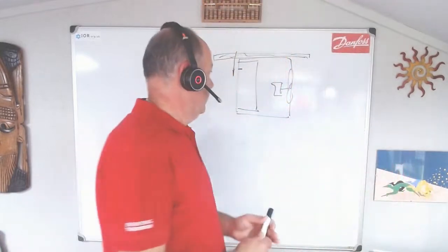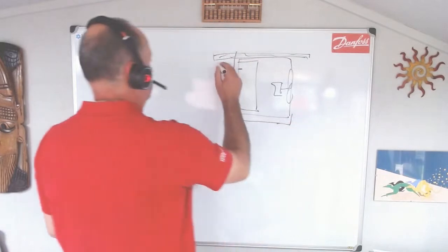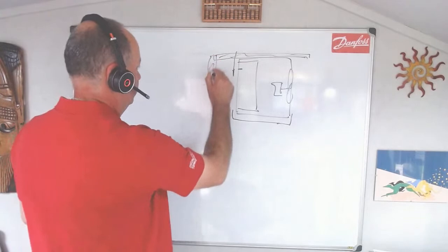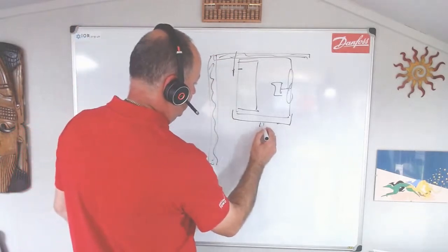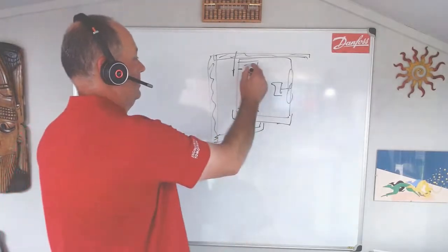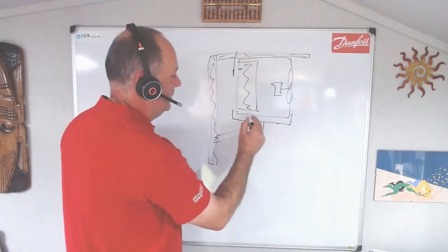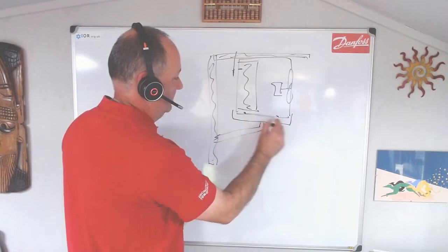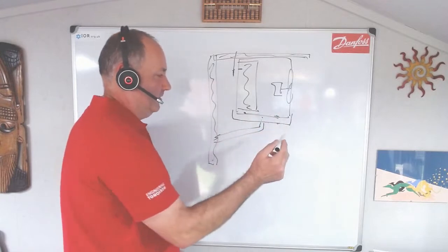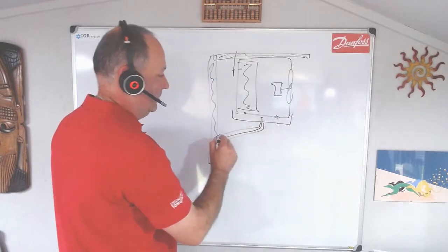Okay, drain line heaters, must they operate all the time? Now, obviously, let's play on the whiteboard a bit more, as we've got the picture of our evaporator up. Let's do the cold room wall a bit better. So we've got our drain off the cooler. As we defrost the coil, all the water that we've generated from the ice goes into the drain pan. We've also got a drain pan heater in here, and then if it's a negative temperature room, we should have a heater tape in the drain.